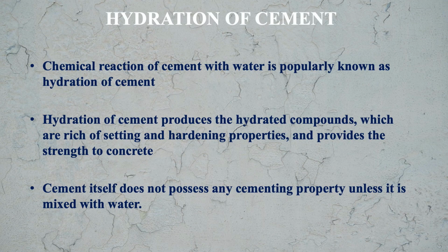Cement itself does not possess any cementing property unless it is mixed with water. Means till cement is in dry state, it is not having any cementing property. When it is mixed with water and that chemical reaction takes place, then the hydrated compounds that are formed because of this reaction give the cementing property to the cement.